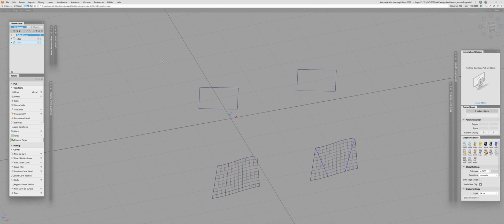So I'm aligning with G2 constraint, and in the alignment type, as you can see, automatically it is the edge. So the edge alignment comes by default. I believe you already know this. So let me do that. Let me remove the extra C0. Now, as you can see, this is just quite a common thing. So it works as intended, and on both sides you're going to see the start edge and end edge.